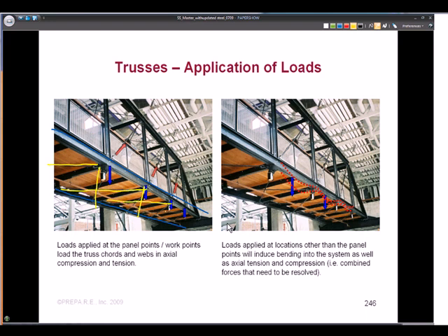That's our horizontal diaphragm. If there's an earthquake load or an internal wind pressure pushing on this, that's how we get the horizontal loads back and keep this truss from racking. You can also see it up above. So these trusses are braced at the top and the bottom with a horizontal diaphragm.